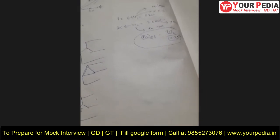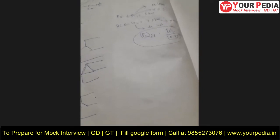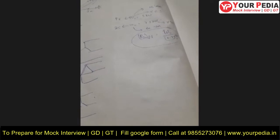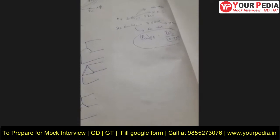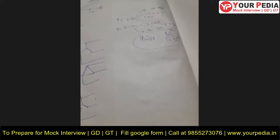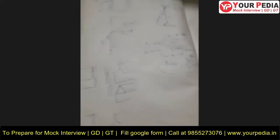You are asking about critical resistance, sir. Yeah, critical resistance. Critical resistance is a resistance above which voltage build-up can't be done, sir. The field winding resistance should be less than critical resistance for voltage build-up, sir.